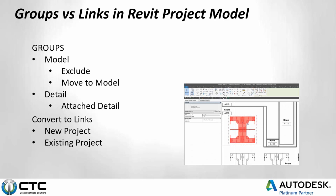So again, we'll first talk about groups. We'll talk about the model groups and how we can exclude some elements. We can move some models. We'll talk about how to create the group and manage those and what can be done to copy those and what not to do. We do have some things about some processes that we've seen in Revit that people have used, or some issues that have come up because of different techniques that people are using with groups. And we'll also talk about the detail groups and how those can impact a model in regards to documentation. And then again, we'll get into converting the links.